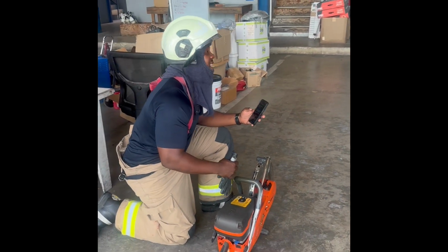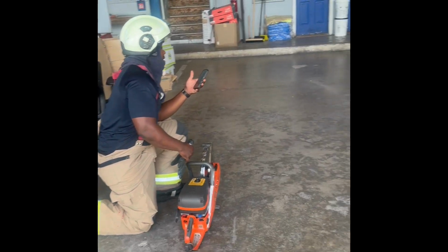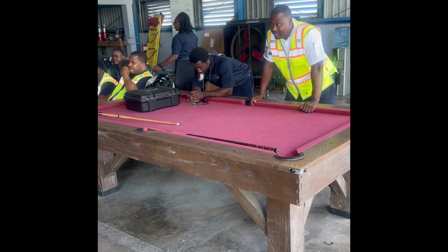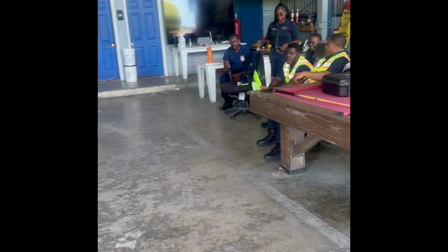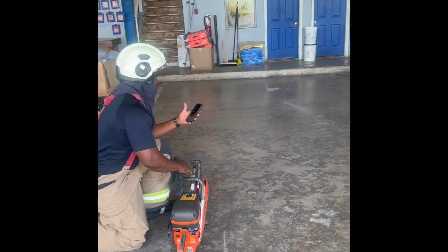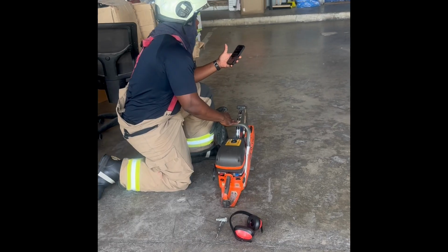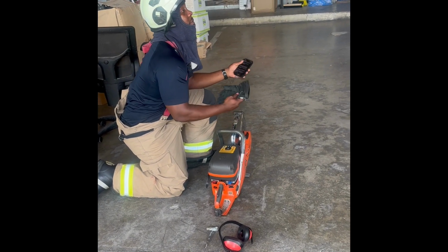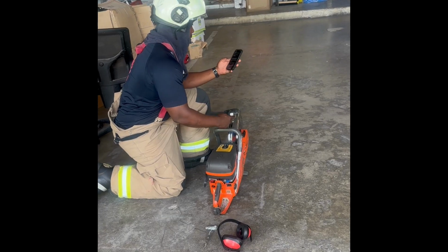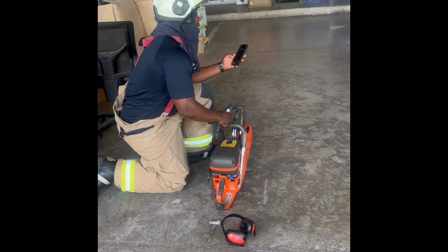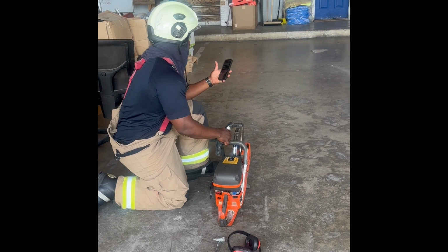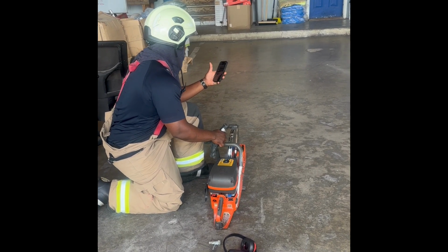All right, so monthly checks when running it. Monthly checks would be holding the saw in a downward position, running it for 3 minutes, and operating under load within those 3 minutes. That would be the monthly check. Another safety precaution is to check your environment before you use and operate it. And in case of refueling, you want to move 10 feet from where you're refueling it.